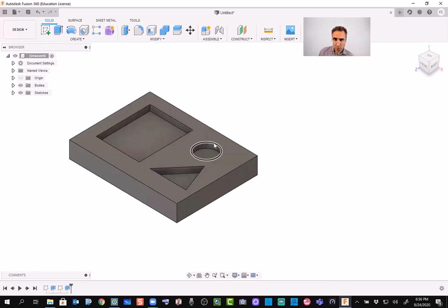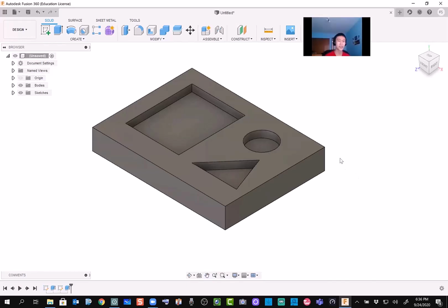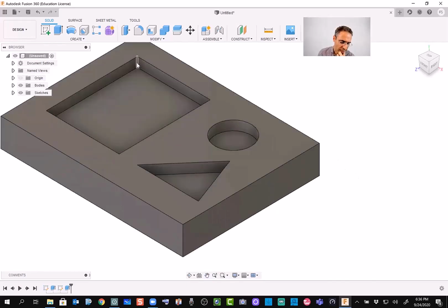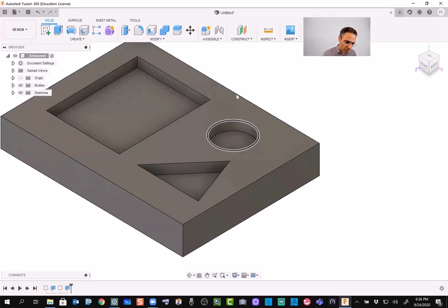Now it's time to do a milling for this one, but do you guys think that we can machine this one down and create these pockets? Is it okay to do that? You need fillets. Great, yeah. This sharp corner, we cannot really machine that and create those. Our tool is going to say, sorry, I cannot do anything for you. So, as Jesse pointed out, we need fillet.